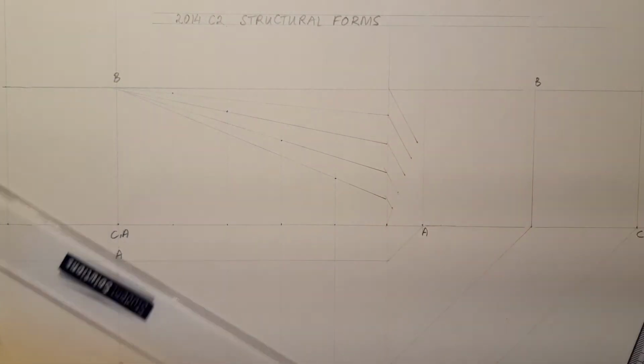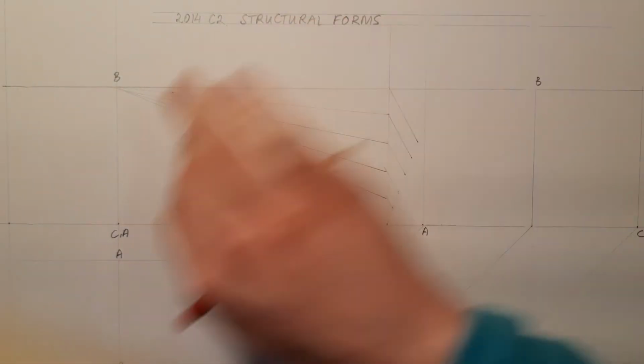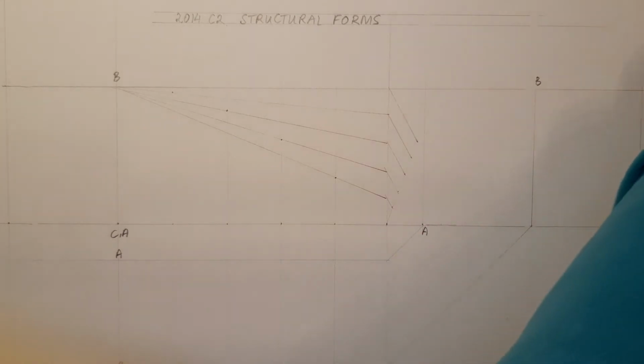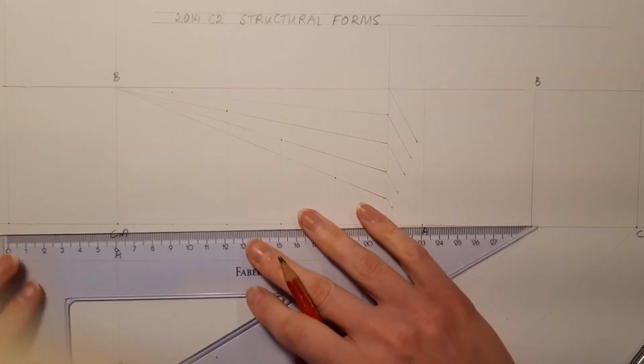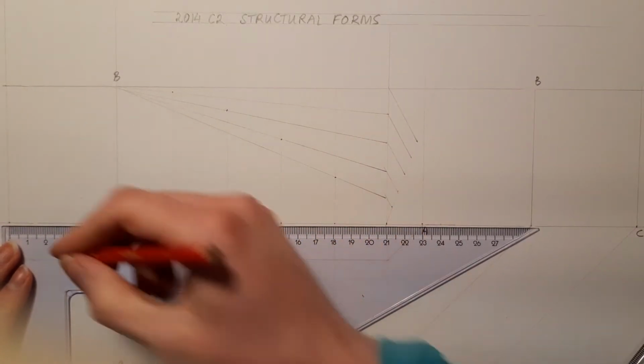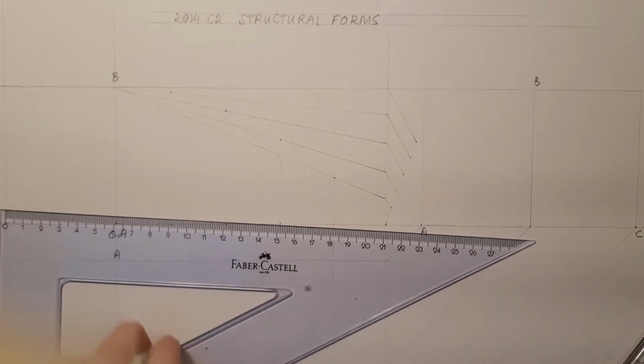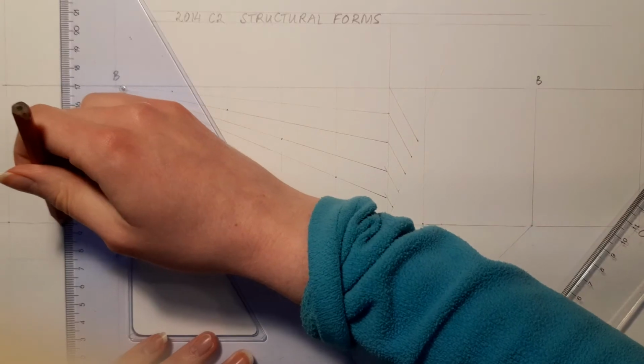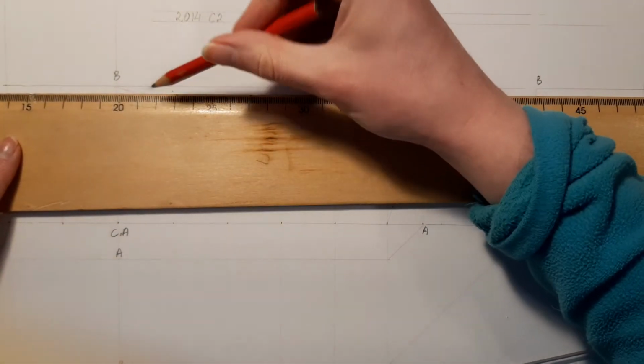Okay, so as you can see, the curve is coming in. But on the left-hand side, you have 60 millimeters as well. So that can be divided up into another 2 places. And you can find another point on the left-hand side. Another 2 points, should I say, on the left-hand side. All I'm doing is transferring the height across.